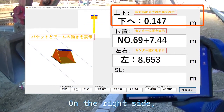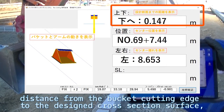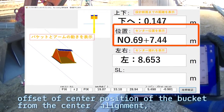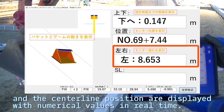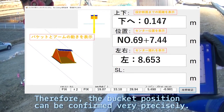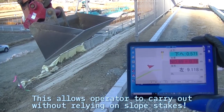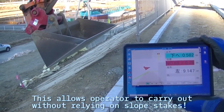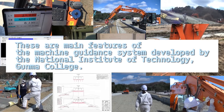On the right side, the distance from the bucket cutting edge to the designed cross-section surface, the offset of the center position of the bucket from the center alignment, and the center line position are displayed with numerical values in real time. Therefore, the bucket position can be confirmed very precisely. This allows the operator to work without relying on slope stakes. These are the main features of the machine guidance system developed by the National Institute of Technology Gunma College.